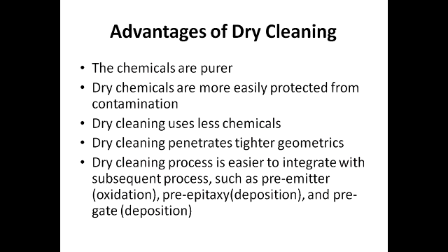The advantages of dry cleaning: the chemicals are purer. Dry chemicals are more easily protected from contamination. Dry cleaning uses fewer chemicals. Dry cleaning penetrates tighter geometries, and the dry cleaning process is easier to integrate with subsequent processes.